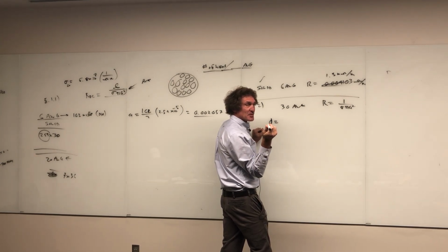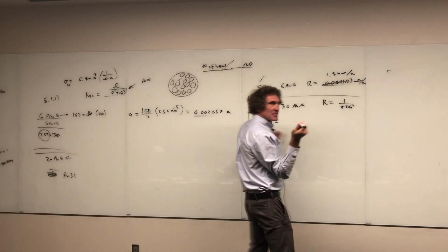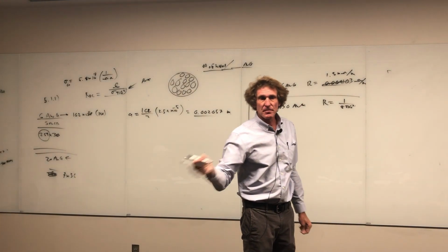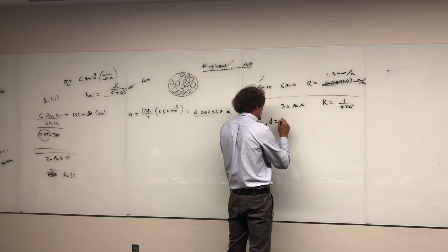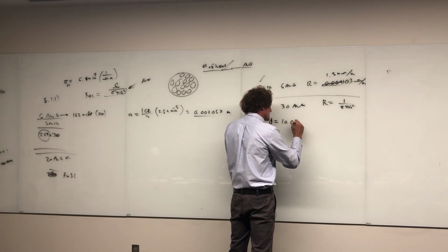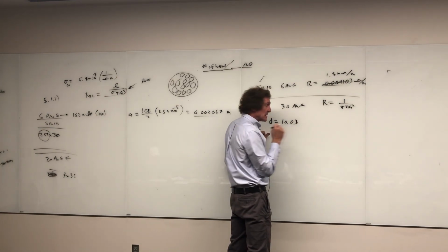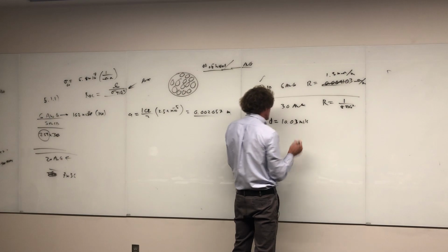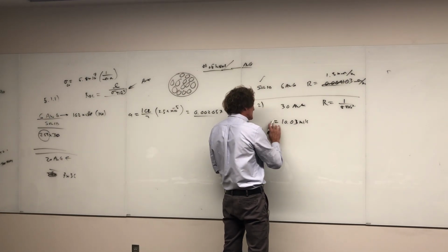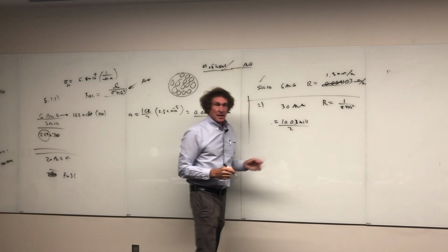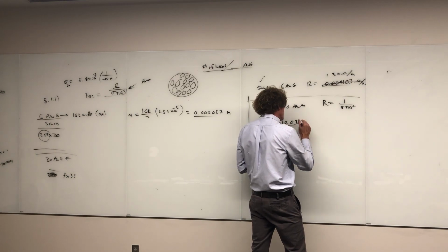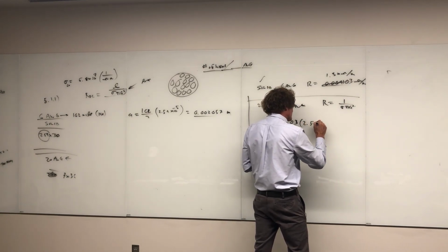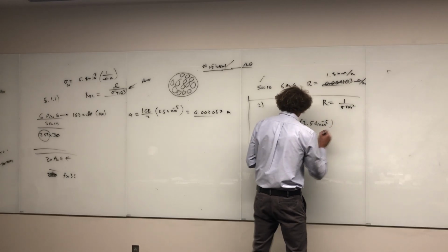I put that up there on purpose so you wouldn't have to look on the internet. What is it? It doesn't have 30. Isn't 30 down below there? 30 diameter in mils is 10.03. 10.03 what? Centimeters? That was in mils. That's mils. Okay. All right. So that's the diameter. So what I'm going to do is then take the diameter by 2. Now I've got the radius, and now I'm going to multiply that times 2.54 times 10 to the minus 5th. And this will put it in meters.